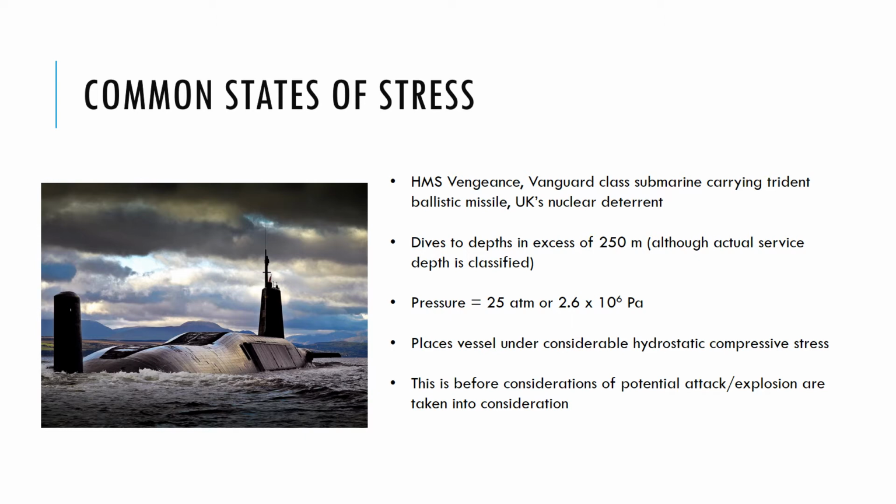Now, this is interesting from an engineering aspect because often we have to think about the design of vessels that can transport various things and are able to withstand very high pressures. You think about, there are a number of examples. You think about an aircraft that has to operate in low pressure, but has to be pressurized in order to keep the inhabitants of the aircraft safe. The walls of that aircraft have to be able to withstand the pressure there.